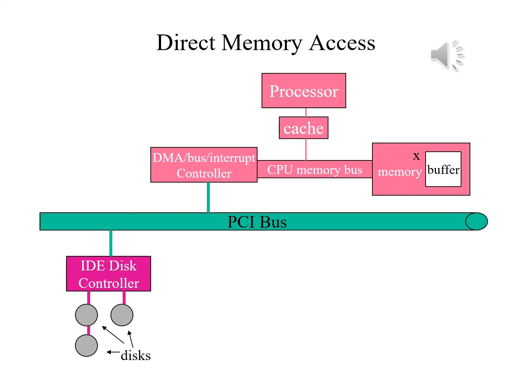It's initiated by the host system writing a DMA command block into memory. This command block includes a pointer to the source of the data being transferred, a pointer to the data's destination, and the number of bytes to be moved. After doing this, the CPU writes the command block's address to the DMA controller and goes back to its own work. Then the DMA controller takes over the job.